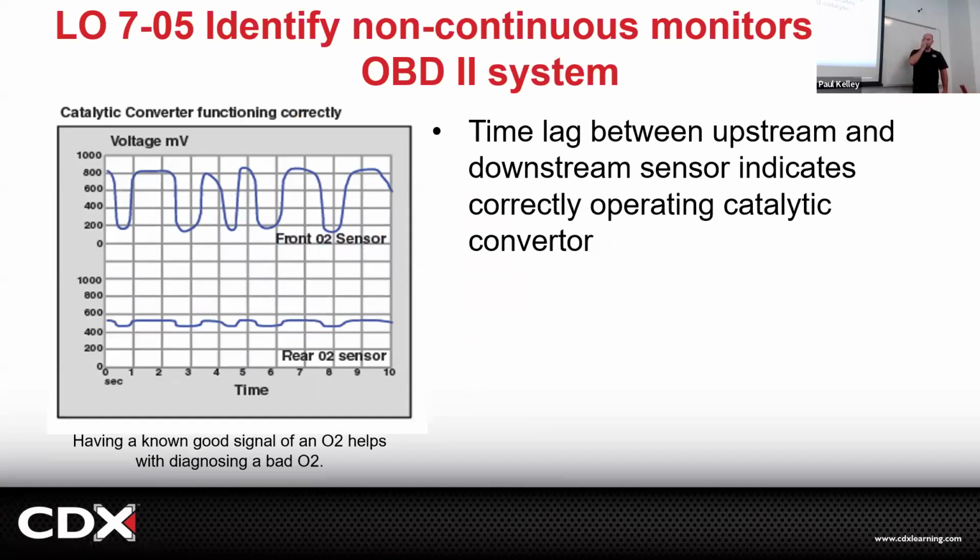You ready to have your mind blown? A threshold. A threshold meaning if you're better than this number, you pass, and if you're lower than this number, you fail. And typically the threshold is going to be about 1.5 times the emissions level of perfect. So if your vehicle was in 100% perfect condition, it's going to emit exactly what it's supposed to. We allow that catalytic converter or that EGR, not really so much with the evap, but a lot of these things, to degrade slightly because we know they wear with time, just like us.